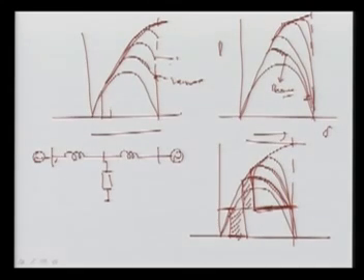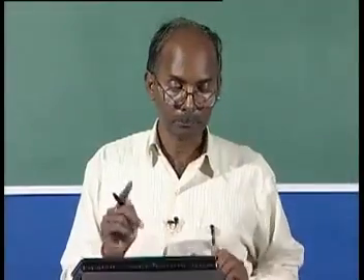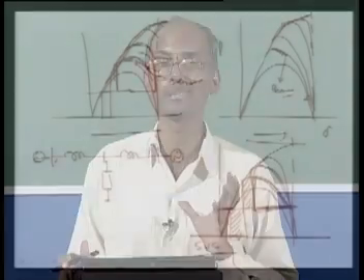Now the same, if you see here what we are going to do. This value is now hitting, and now this value is not 0 here, we are getting this characteristic, more. So this is not going to be 0, earlier it was going to 0 here, so we have more margin. So we can say the STATCOMs are better in terms of dynamic performance than SVC, but the STATCOMs are expensive compared to SVC, and that's why the SVC is very popular and very simple also.